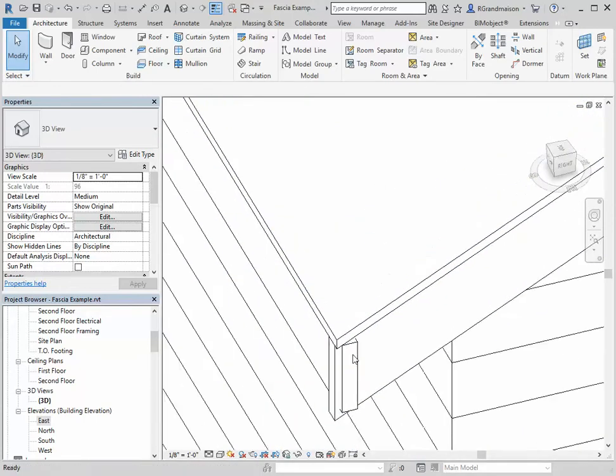That gives you a little bit better realism for how the shingles actually should meet on the outside of the building, because they should extend a little bit into the gutter and not allow the water as it runs off of a roof, whether it's on the rake or the eave side, to leave stains or marks on your woodwork.